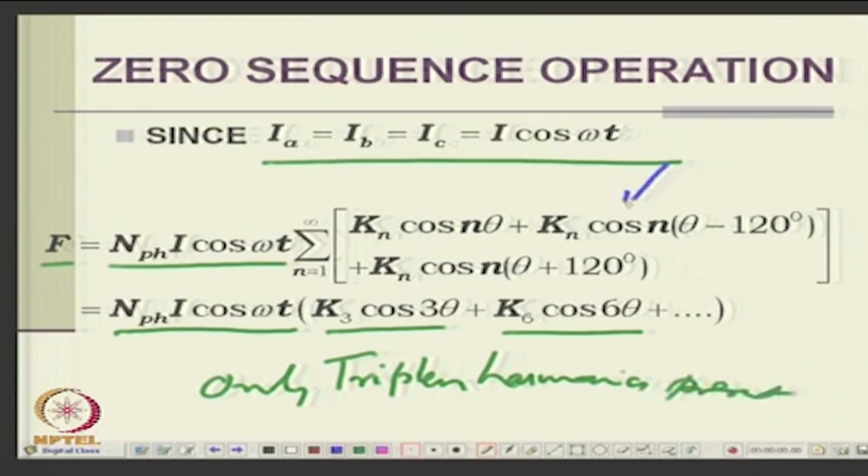Okay. So, I want you to check this, will you? You may confuse yourself, because if A winding has a set of MMF sitting there, B winding will be the same after 120 degrees for the fundamental, right. So, you will see that all the fundamentals will vanish, all the fifth harmonics will vanish, all the seventh harmonics will vanish, only third, ninth, like that will be there. Third, ninth I am telling you, I did not say sixth.